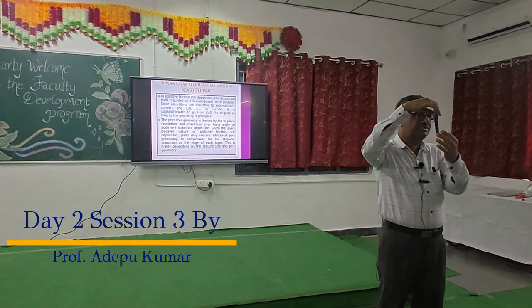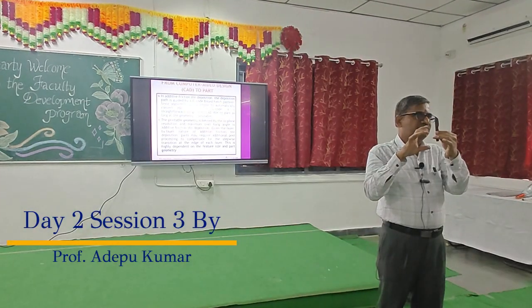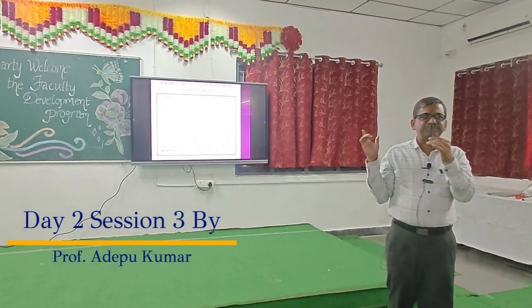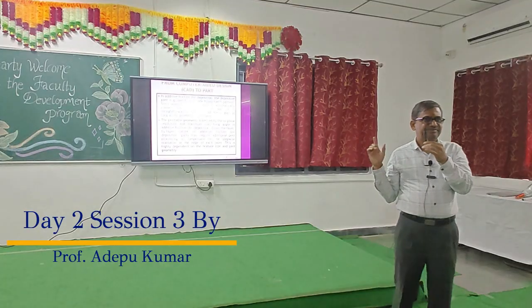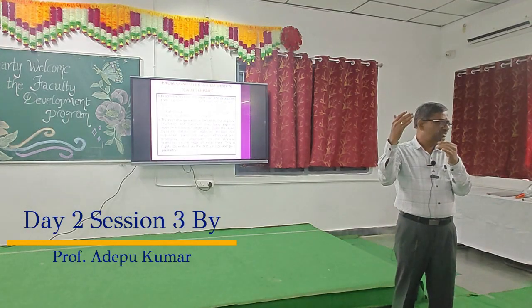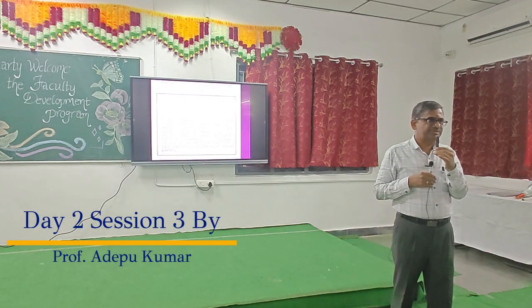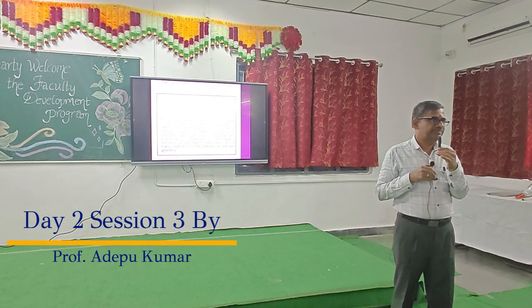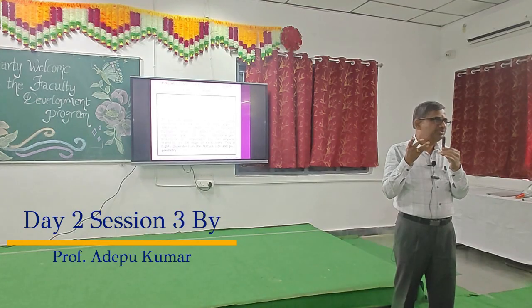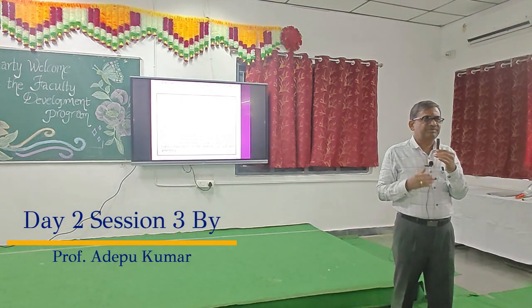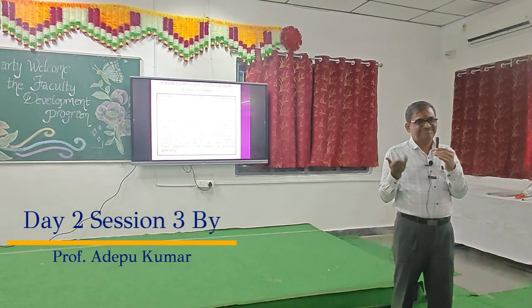Due to that, there should be buckling. So the height is limited in this process, not equivalent to the fusion additive manufacturing or powder bed fusion process. There are also some issues when you go very high: the bottom will be overheated,